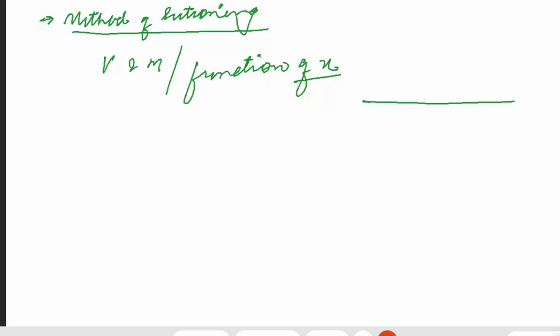We have this simply supported beam. It has a pinned support on one end and a roller support on the other end. It has, let's say, a point load, and a uniformly distributed load of intensity, let's say, W per unit run, for a distance of, let's say, a. Now I want to know how the pattern of the shear force and the bending moment varies. For that, I have to make the equations of shear force and bending moment functions of x.